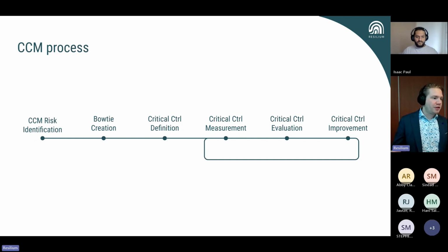So typically what most organizations do is try to identify which of those controls are really the most essential, the really key controls or the critical controls in that process. And then if you are very selective, you typically end up having maybe 2, 3, maybe 4 of those critical controls in your bow tie. And the idea is that once those critical controls are well under control, we have a pretty good grip on that risk. And then we can also actively try to monitor those controls.